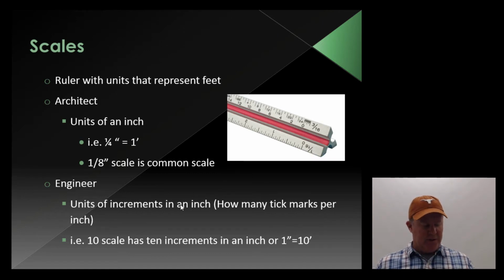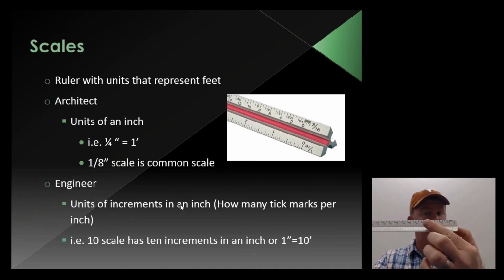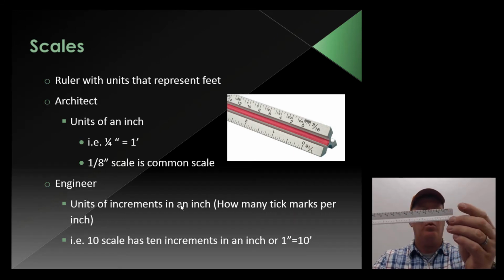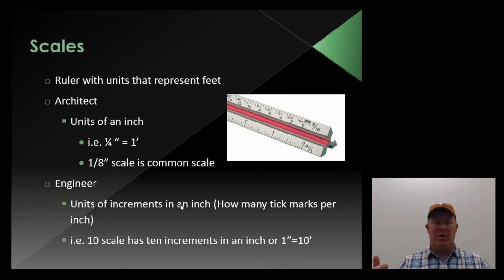Versus an architect scale, like here we have a quarter scale, it's going to read right to left from your perspective. A 1/4 inch on the scale or paper represents 1 foot on the project or the site. So we have a lot of exercises that we go over, making sure that students can read the scales and actually read tape measures.